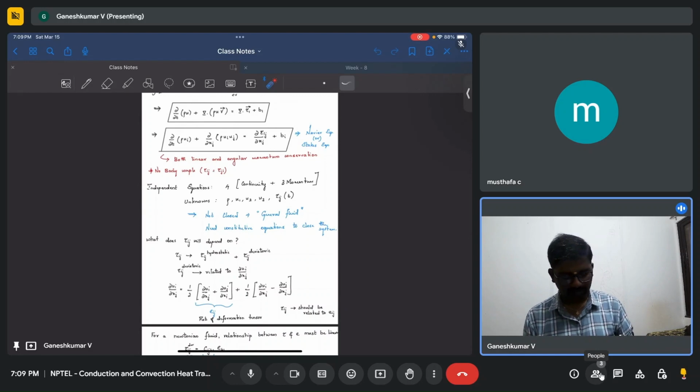So in this equation, this is a momentum equation, a general equation. The only thing is the unknowns are density and velocity. In addition, we also don't know the shear stress, or the stress tensors. Basically this is a tensor, so you will have 9 components, but since it's symmetric, you will have 6 components. So there are an additional 6 unknowns. So we need something to close this equation.